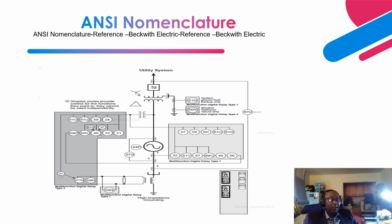Next is 60FL, and that is fuse loss. The fuse that is connected on the high side of the VT, located at the terminal of the generator: when the fuse goes out, this element detects the unbalance of voltage measurements.